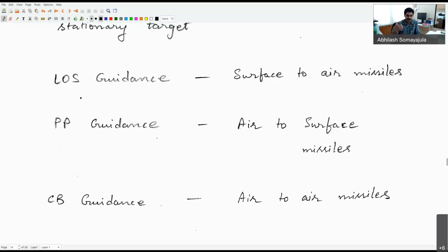Okay. So these 3 different fields of surface to air missiles, air to surface missiles, and air to air missiles gave rise to these guidance laws, but they have found applications in different other fields. And we are particularly interested here in applications to the marine field. So when we are bringing these concepts and discussing them in a ship dynamic positioning course, the reason why they are making their way here is that the same guidance also applies if I want to maintain a formation control or an underway replenishment. So for such exercises, the same control logic, the same guidance logic, can be applied.